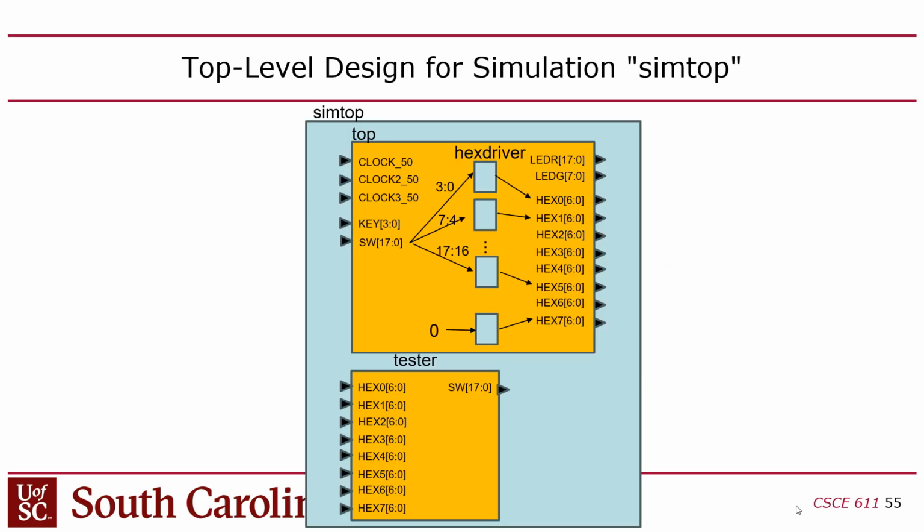However, we also want you guys to create a test bench, which means that you need another top module for the simulation mode, right? So SystemVerilog always has to have a non-synthesizable test bench of some kind, as well as the synthesizable code that you want to put on the FPGA, right?